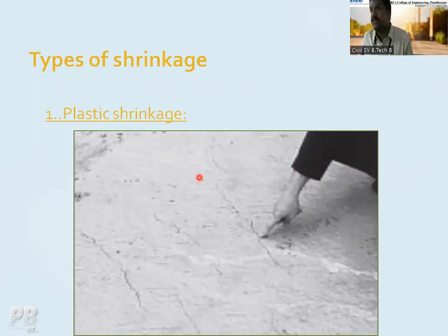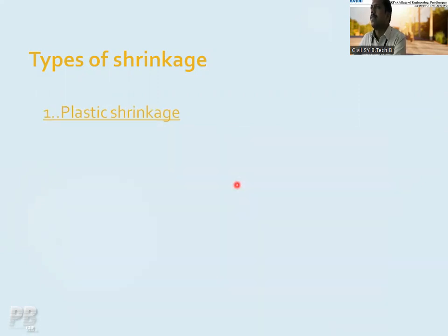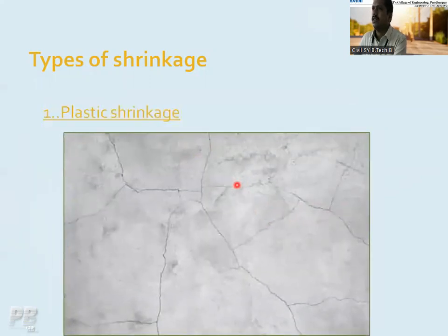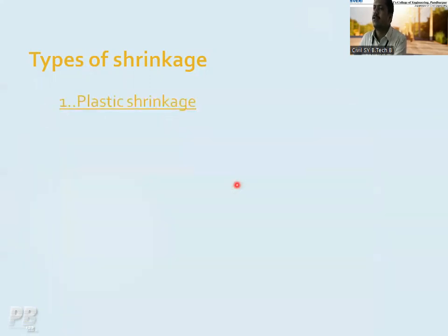And when it is in fresh condition, plastic condition, at the early stage, you have just poured the concrete in the concrete body, in the formwork, and immediately after that, you have seen the water start evaporating from the top surface, and there is a formation of early cracks. Okay, plastic shrinkage. I hope everyone has understood. समजला plastic shrinkage? Yes, sir. Early cracks you are going to see.